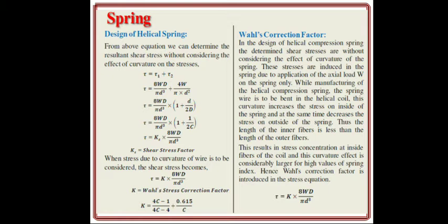Hence the Wahl correction factor is to be introduced in the stress equation. So tau is equal to K into 8 into WD divided by pi d cube.